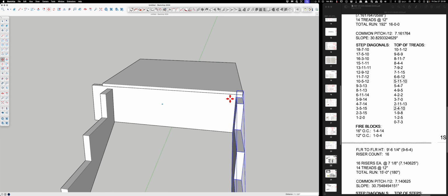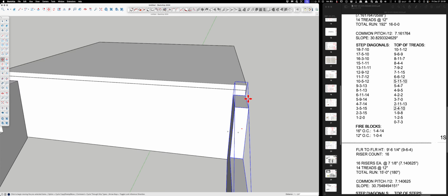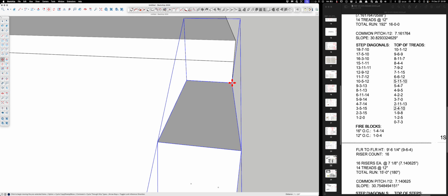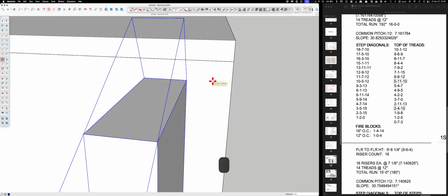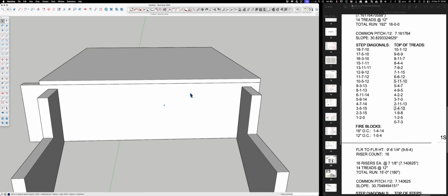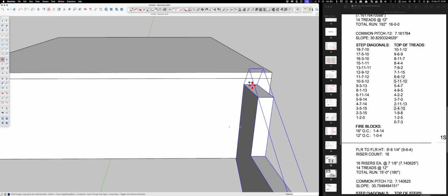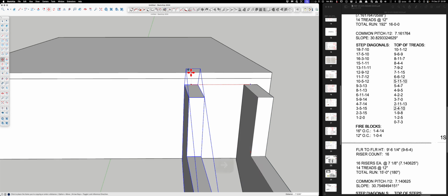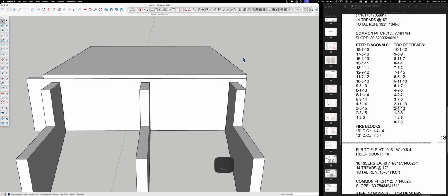Oh. I was going to have it automatically hit like 2 divide, and then it would put one in the middle. But I'm not exactly sure now, since I'm using 1 3/4 and not 1.5. So I don't get to do it that way. So now I'll just have to find the center this way. Move copy. Find the center of this. Hit the red, and then this top piece should have a center. Boom. There it is. All right, so now we got 3 sets of stairs.